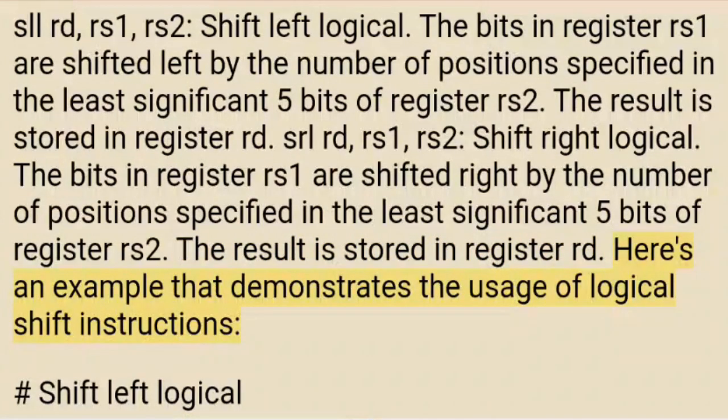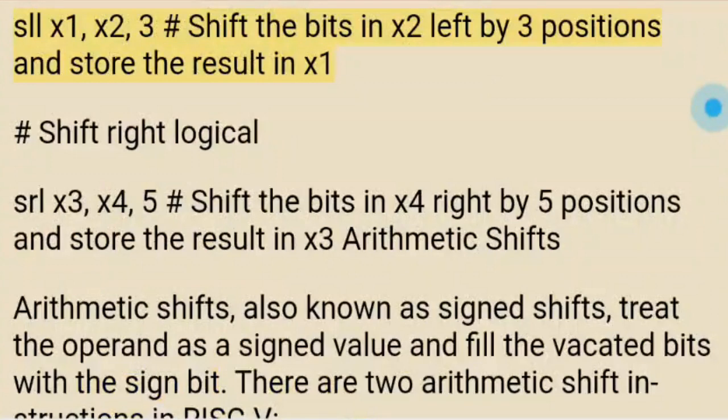Here's an example that demonstrates the usage of logical shift instructions. # Shift left logical: SLL x1, x2, 3 # shift the bits in x2 left by 3 positions and store the result in x1. # Shift right logical: SRL x3, x4, 5 # shift the bits in x4 right by 5 positions and store the result in x3.